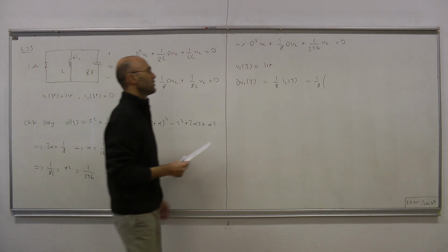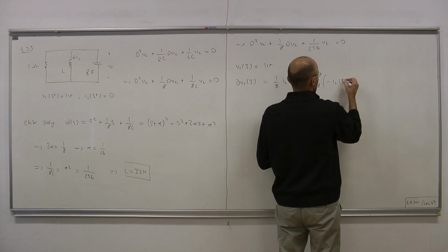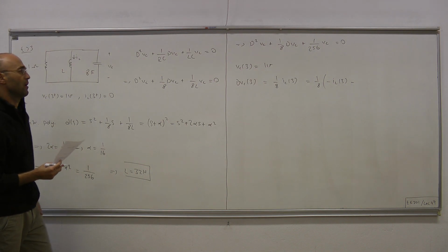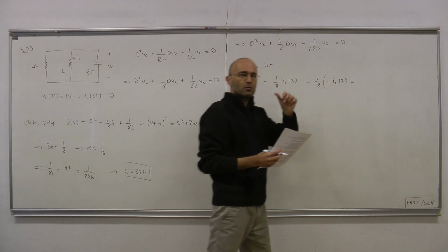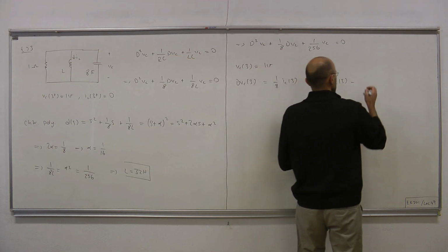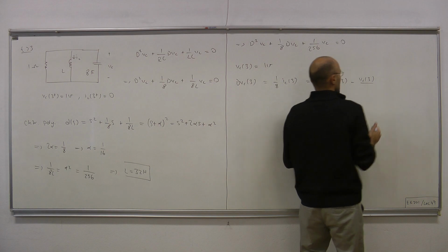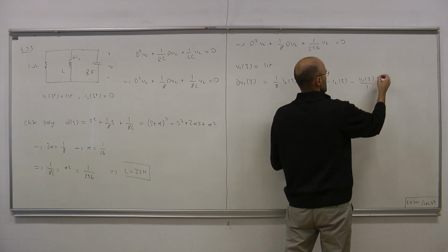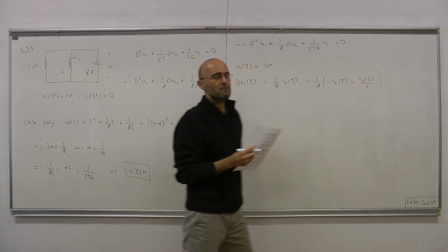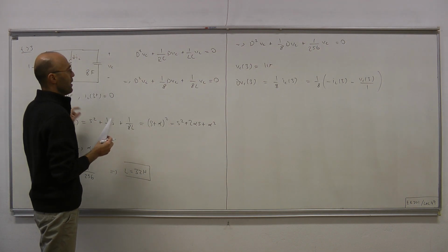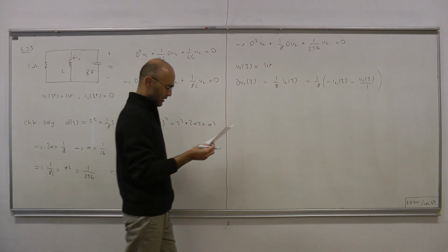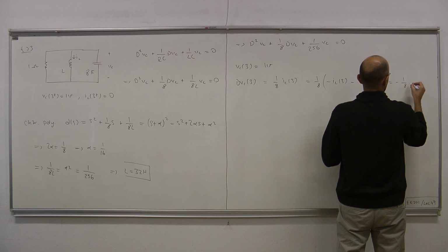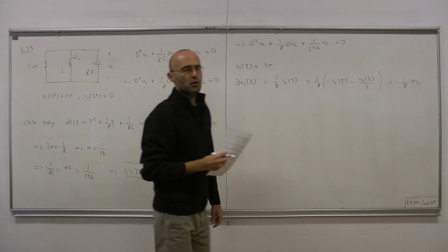Therefore IC you can write as minus IL(3) minus IR, the resistive current. And resistive current is resistive voltage divided by resistance, and resistive voltage is no other than the capacitor voltage divided by resistance 1. Now IL(3) is 0, Vc(3) is 1, therefore we can figure out dVc(3), which yields minus 1 over 8 volts per second.